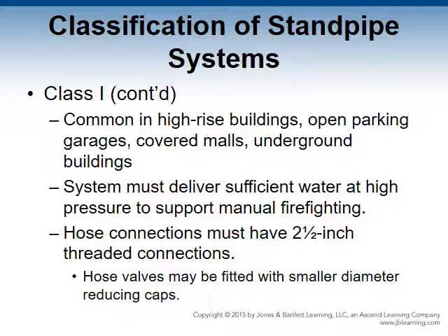Hose connections are required to be a minimum of 2.5-inch threaded connections. The hose valves are commonly fitted with 2.5 to 1.5-inch reducer caps to facilitate the use of small diameter hoses found in the standpipe packs.